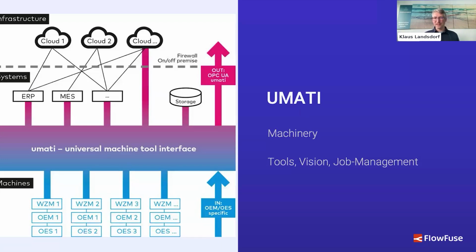That means you can send out a job via OPC UA to your machine. You have a job list on the machine. You can control how that job list is working at the end on the machine side. And you get also process values, you get results. It's all defined, and you can bring to your machine material, personnel, equipment, all these things what ISA 95 defines for MES or manufacturing operations management.